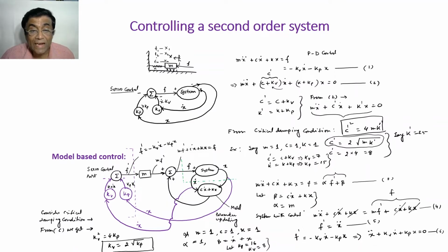So for that you require a model, right? Understanding the model. And if you identify, okay, these are the parameters, unnecessarily I will not try to control them, rather I will try to just upgrade them. So this is parameter upgrading, upgradation is taking place in this part, and only in this part actual control is taking place. The idea is this will make the controller design simpler.